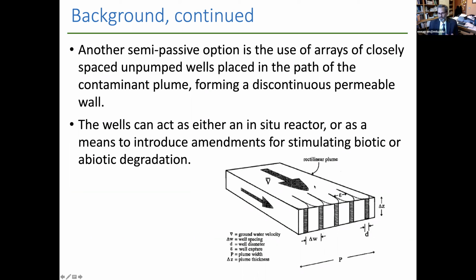These wells can, similar to the PRB, function as an in situ reactor. So we could put activated carbon or some other reactive material in there. In that case, we're interested in the flow into the well and treatment inside the well, or they could be like the PRB, releasing amendments into the subsurface to stimulate abiotic or biotic reactions down gradient from the well.